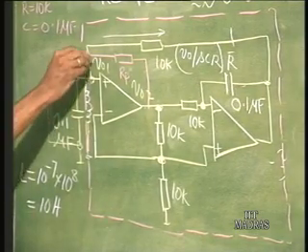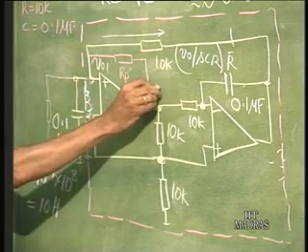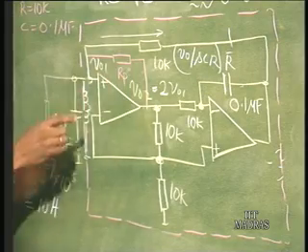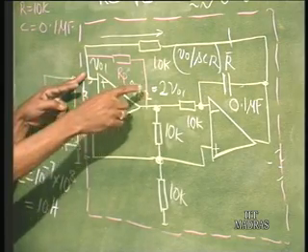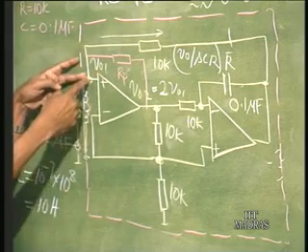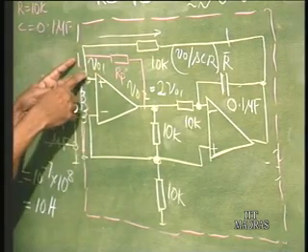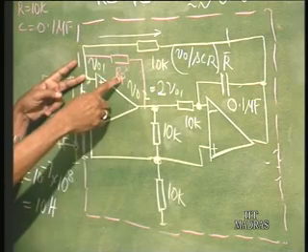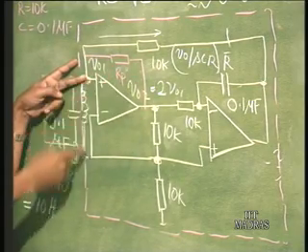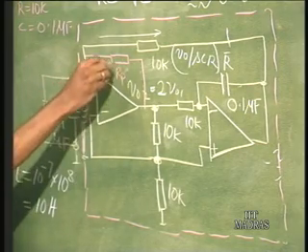How do I simulate a negative resistance? We have V naught 1 here and V naught 2 is equal to twice V naught 1. So, if I put an RP here, the current will be V naught 1 minus twice V naught 1 by RP. That means, from here to ground we have minus RP getting simulated. RP is the effective resistance from here to ground. So, across this inductor you have a negative resistance that is simulated.